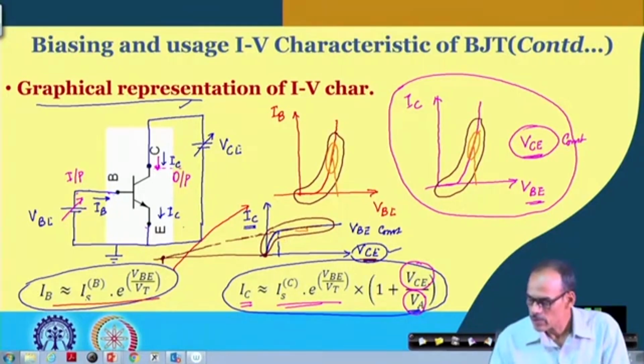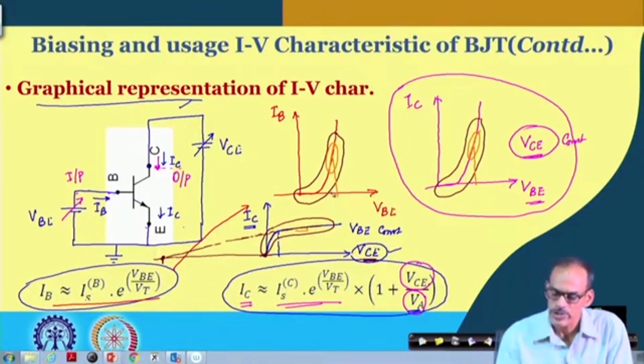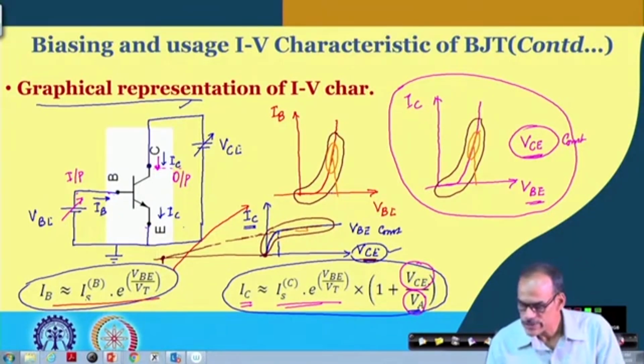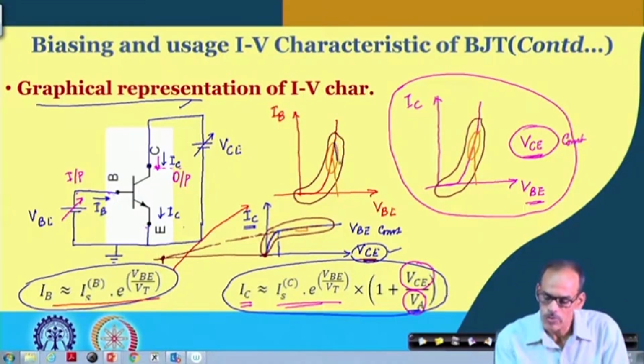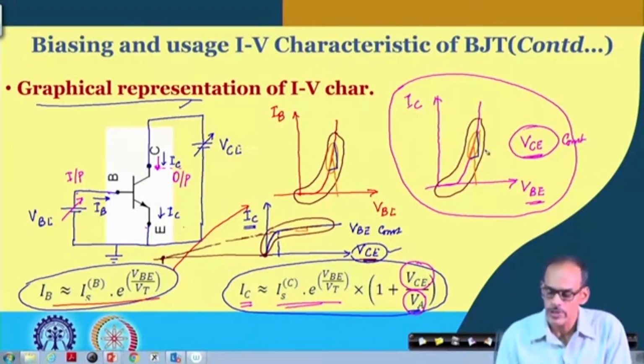And we will also be seeing that apart from this large signal behavior, what is important is the slope of this line. Whenever we go to the small signal model or equivalent small signal model, as we have discussed for the diode, the slope of this line is important, and equation-wise the slope of this line is the change in IB with respect to VBE.